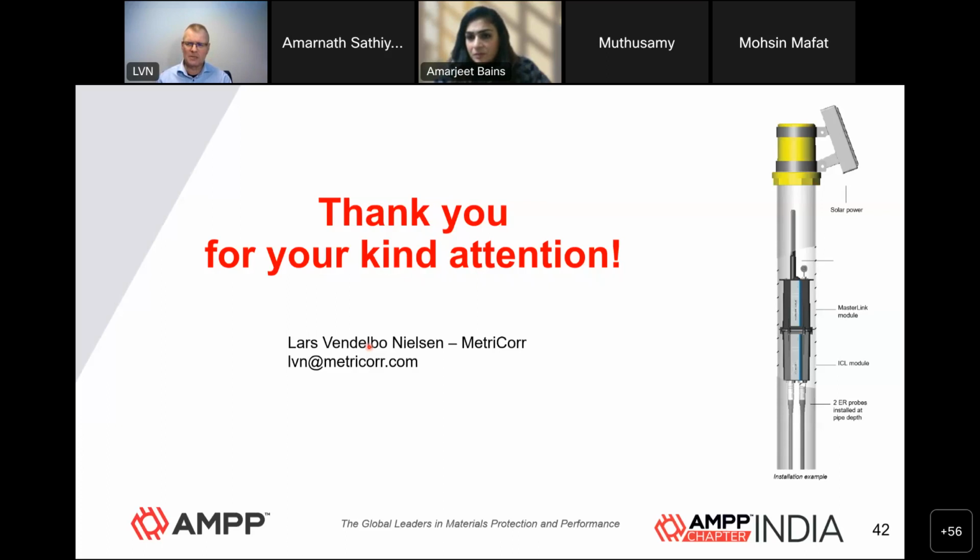There might be some limitation in that you need a number of coupons along the pipeline in order to make this kind of evaluation. But on the other hand, if you really think hard, and we can maybe discuss that another time, if you have a variety of different areas or sizes of coating defects on a pipeline, those defects will shield from each other. And you can actually show that the polarized potentials of the different coating defects are not the same.